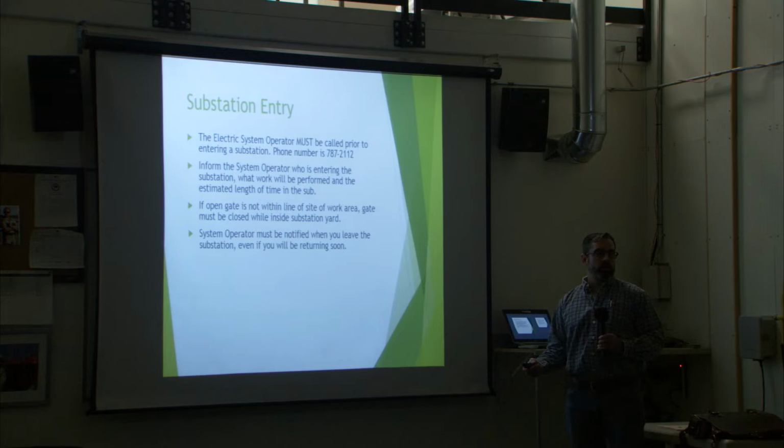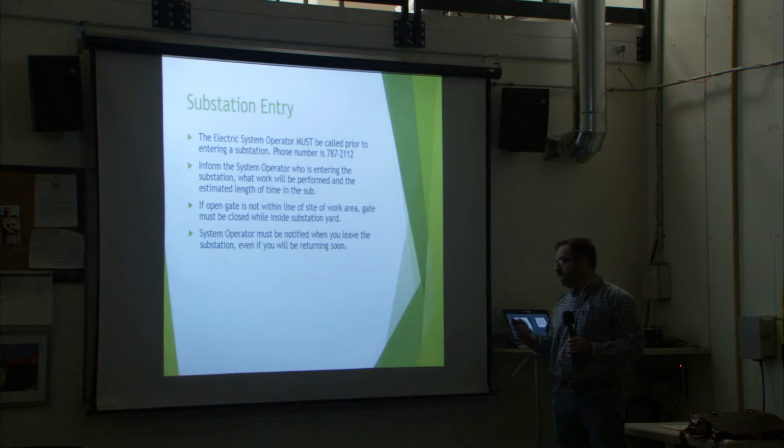Let's say you're a one-man crew inside that substation and you don't call the operator and something catastrophic happens and you're incapacitated. The operator is the only person that's going to know you guys are in that sub. If he doesn't know you're there, he's going to dispatch a crew to see what's going on, but he could be dispatching emergency rescue to the substation if you're incapacitated and you need medical help. So please make sure that you contact the operator prior to entering and leaving the substation.